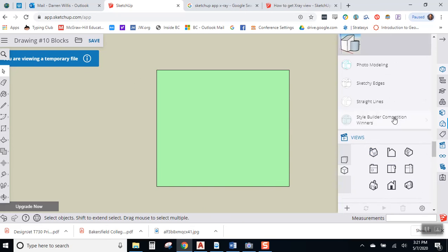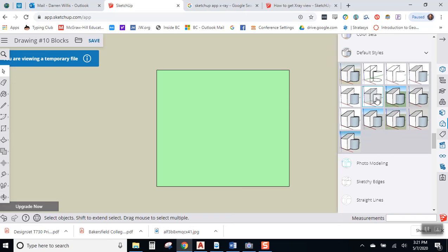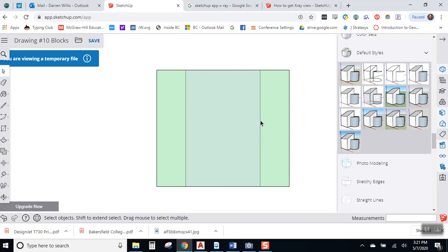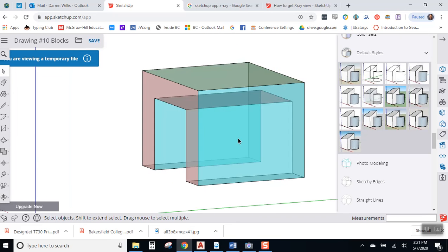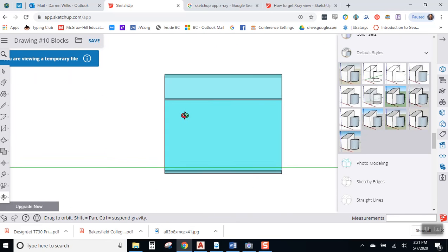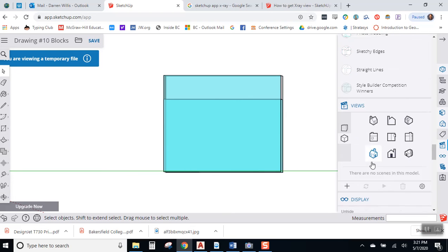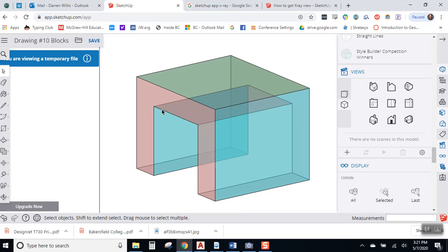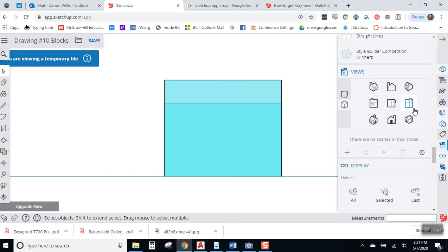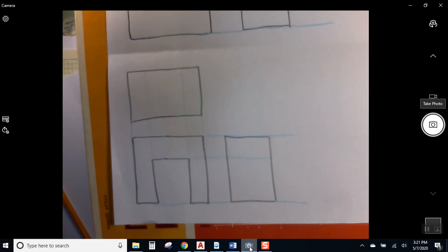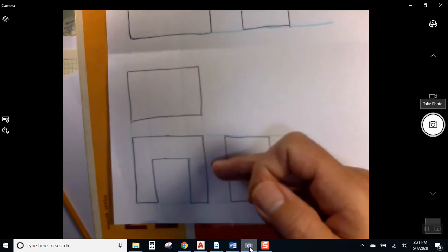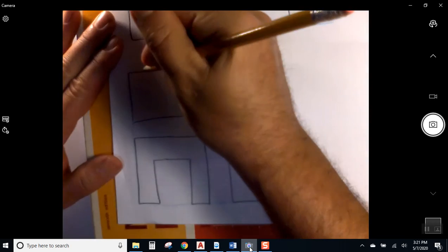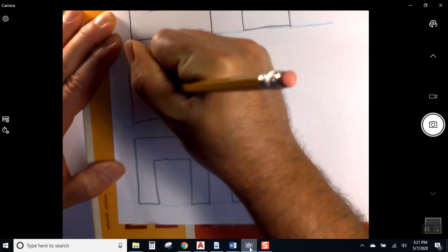But if we go back to the top and we turn on our amazing X-ray powers, hey, there's an edge there, and there's an edge there. And of course, we'll see the same thing when we look at the side, and those edges are being created by the corner up here at the top of our little notch. Okay, so make sure, as you have projected all the corners into all the views, that you don't forget the hidden lines.